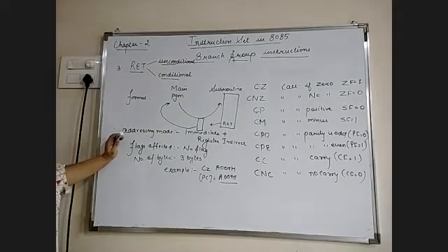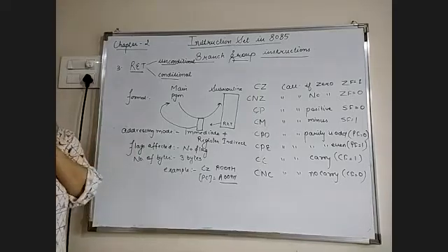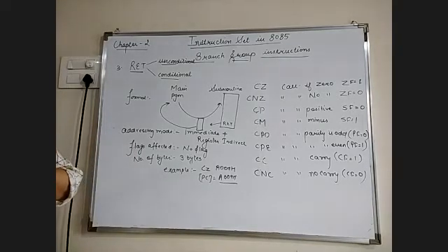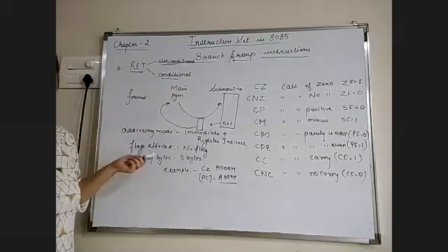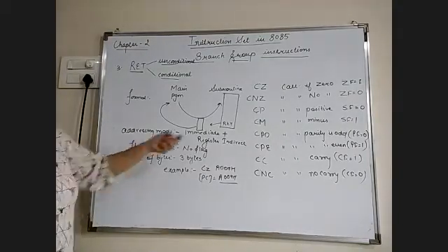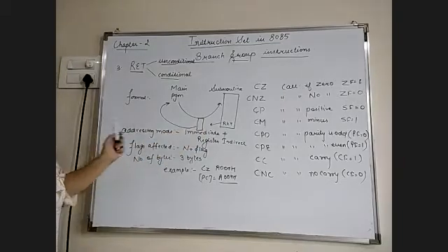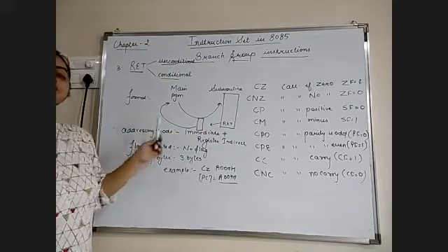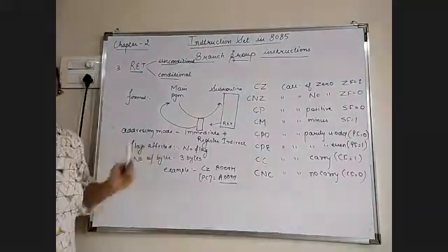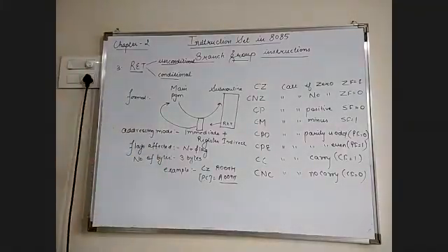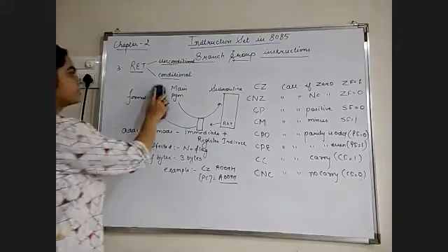That is, we can say the return address, or the address of the program counter, or the value of the program counter. Thus the program counter is transferred to the next instruction after the call in the main program, because the call instruction is already executed by the microprocessor. Then after the return statement, it will get back to the next instruction which is after the calling statement. So that is the meaning of the return statement.